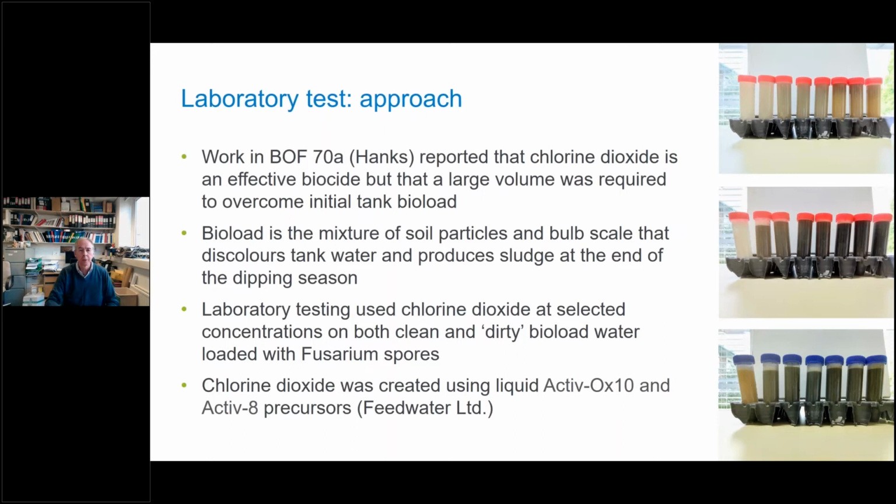So the first stage was the laboratory tests. And we were starting from a position of knowing a reasonable amount, in that BOF 77 had showed that chlorine dioxide is and was an effective biocide. So we knew that it could be used effectively against pathogens, particularly fusarium, as it had been used in other industries, and it's used throughout the medical and food industries. But when Gordon was running these particular experiments, he came up against a problem that we also experienced, in that the very nature of hot water systems, we've got hot water, it's dirty, reduces the efficacy of all these biocides, and chlorine dioxide very much fell into that category.